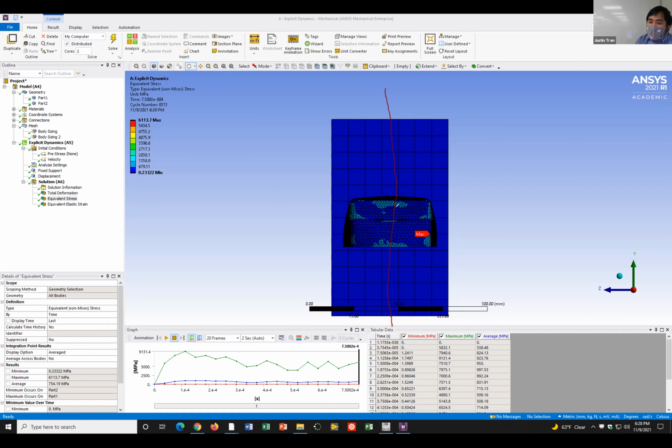But because of that, you can take those elements that you save and pack them into this area again. So it lets you refine a lot more than what you could before, because you're only simulating half of the geometry. And whatever happens on this side is the same as on the other side. Exactly.